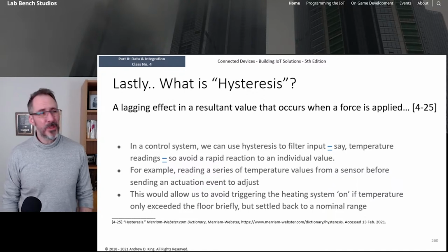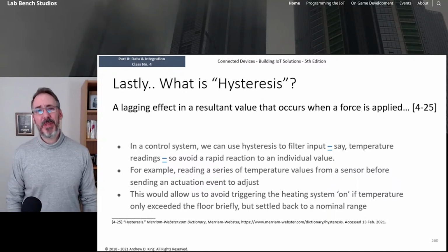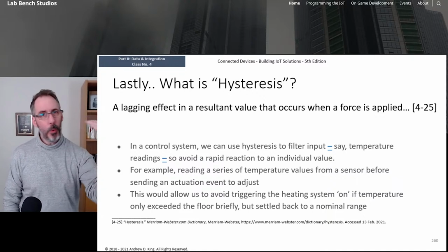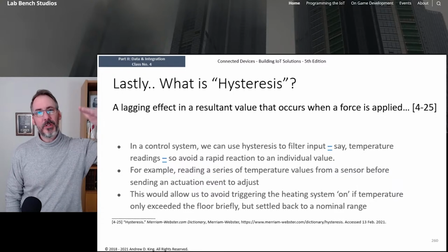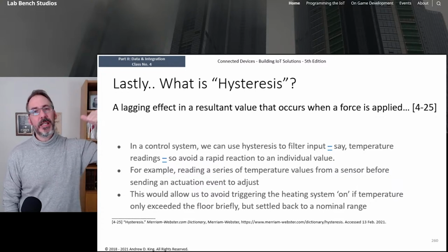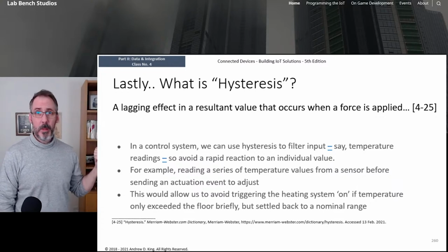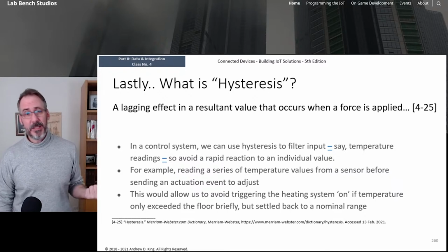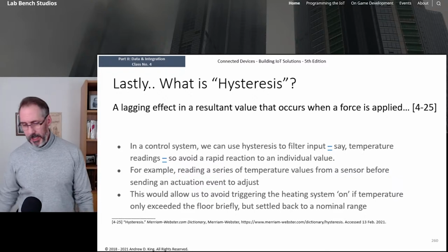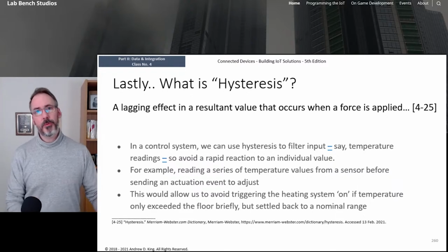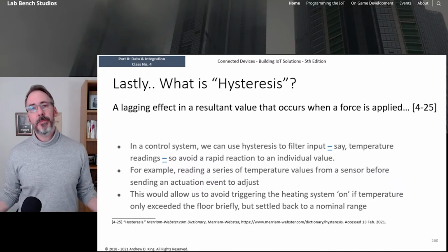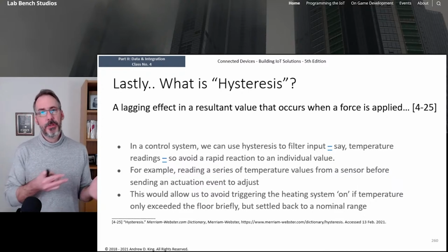The last thing I want to do is, every single time that temperature reading moves like a quarter point, tell the heating system to turn on or off, because it's going to fluctuate so much. I could potentially be sending the heating system a signal to do something pretty expensive, like turn on the boiler, heat up all this water, use a bunch of fuel, and circulate that hot water through one or more zones. That's too much. So I want to use hysteresis to my benefit.